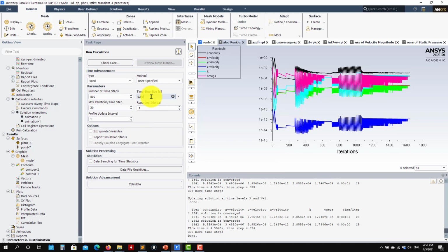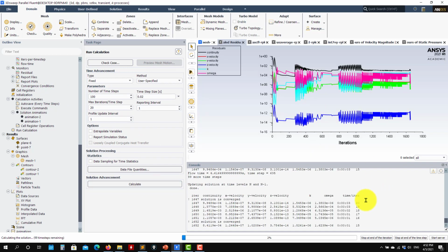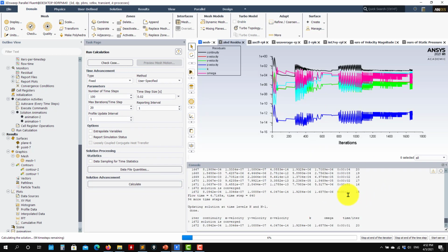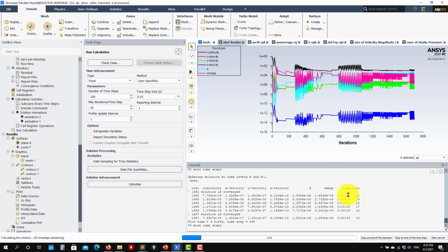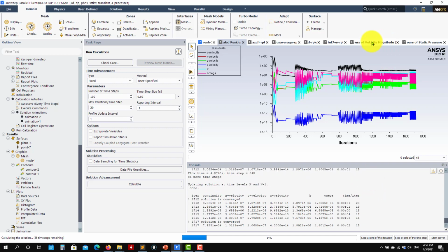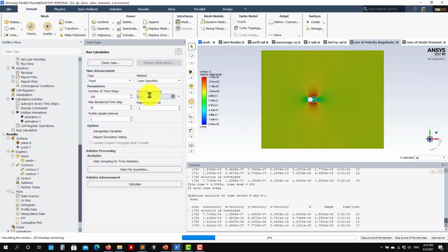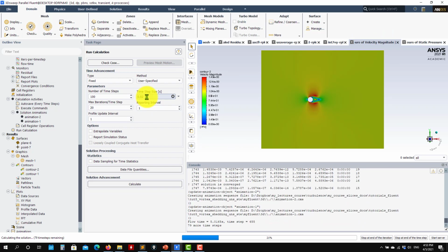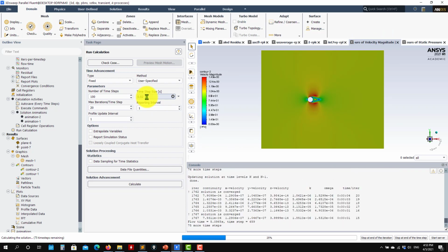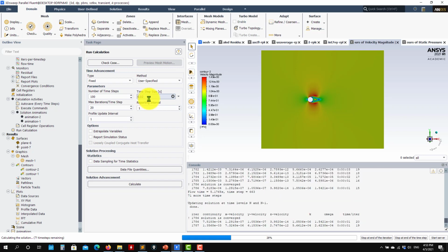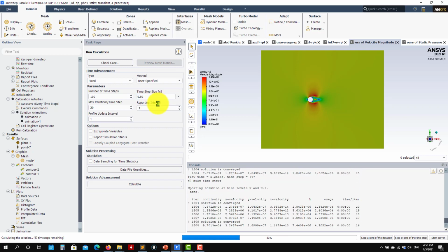So as you go here, your time step, let me increase it to 0.02, and see that the number changes, but slowly. So probably this will be the ideal time step, 5 iterations here. But now you get an idea. So to get 100 seconds in this case, you will need to run like 5,000 time steps.